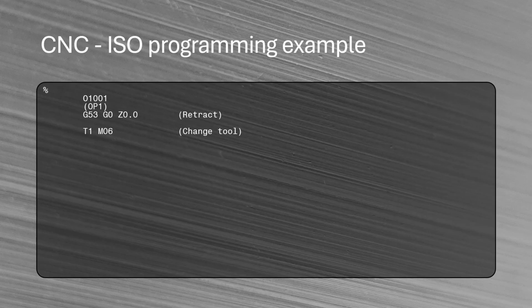After that, we do a tool change. The tool change automatically brings up the tool to do the tool change. And so you may ask, why do we need G0 or Z0 there? Well, the reason is that it might already have the T1 loaded. And if it did that, it would ignore the tool changer command and just continue, and that could cause a crash. And so we need to make sure both of these are true, that the right tool is in and that we are retracted. Then I load in the tool length for that tool, just for simplicity, H1.